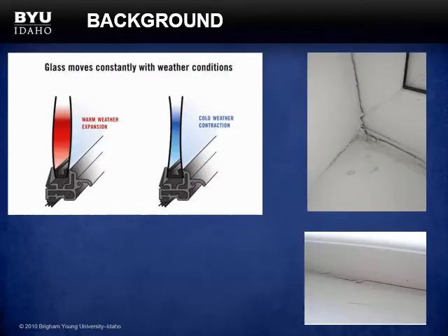Despite its lower thermal conductivity, sealing your window with argon is a bit more expensive, and you will eventually lose the argon because of leaks from cracks created by the expansion and contraction of the window seals due to temperature changes. So, we thought that a better way to manage the insulation efficiency of the air could be managing the gap distance between the window panes.